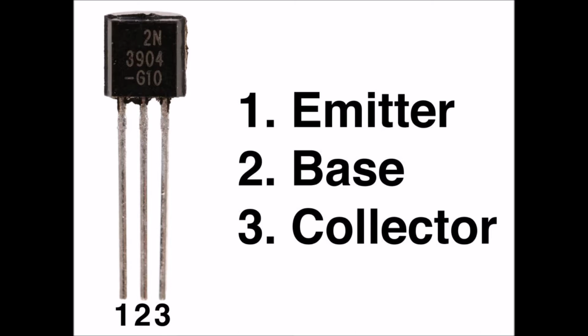Beta. We get an excellent definition of current amplification for real-world signals when we divide the difference in IC by the difference in the current at the base, as we apply a small signal to the base of a transistor with the emitter at electrical ground. Then we get the dynamic current gain for the grounded emitter case. We call this ratio the beta, symbolized as the lowercase Greek letter beta. Once again, let's abbreviate the words "the difference in" as D. Then we have this equation.